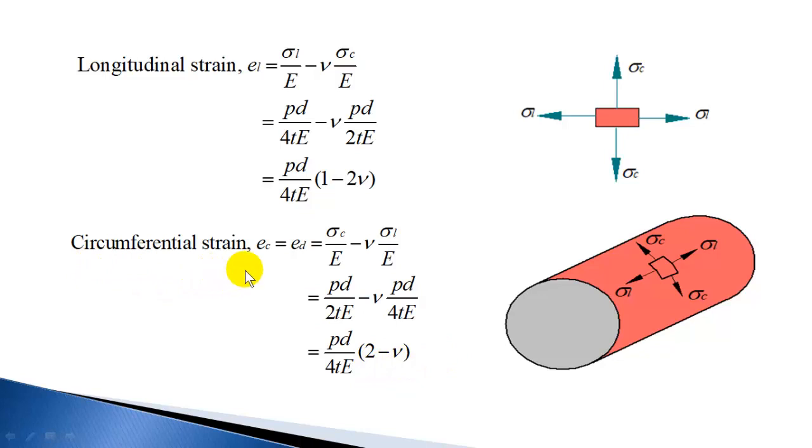So this is circumferential strain, and you can remember circumferential strain as EC, that is a direct strain in a circumferential direction, sigma C by E, minus other stress is producing lateral effect, so minus nu sigma L by E. Here in longitudinal direction you have direct strain due to stress in longitudinal direction, so whatever subscript is, EL, sigma L by E, the other stress is producing lateral effect, so minus nu sigma C by E. So this is a longitudinal strain and circumferential strain or diameter strain.